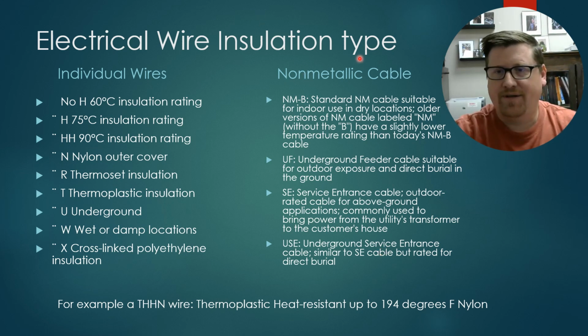You also have non-metallic cable. We're not going to get too heavy into this, right? This is non-metallic sheath cable, I should say. And so this is like Romex, right? These are wires that are a bundle of wires, so a cable that's wrapped in an insulated sleeve, right? And so you have NMB. This is standard non-metallic sheath cable. This is Romex, suitable for dry locations.